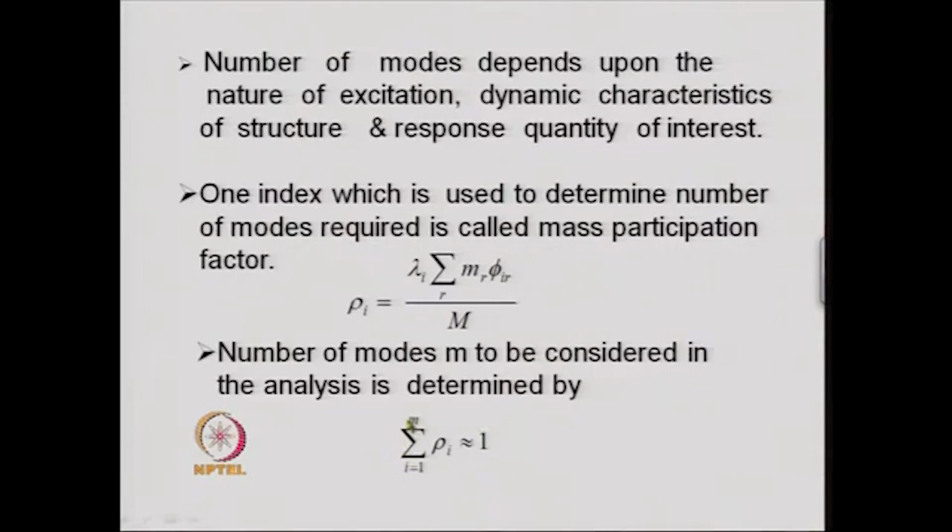For example, for bending moment the participation of the higher modes is very important, because the higher the number of the mode, the more curvature we get into the mode shapes, and since the curvature influences the bending moment, we should not miss out higher modes. So, this general guideline is applicable for finding out a good displacement response.